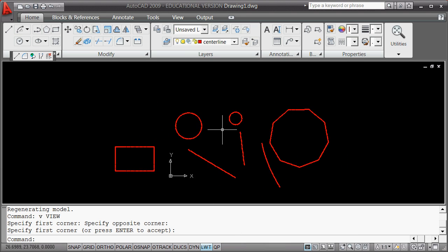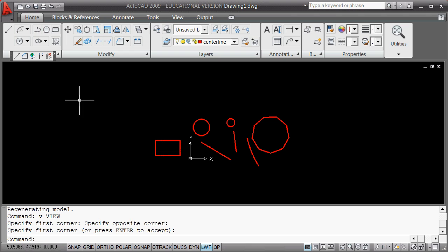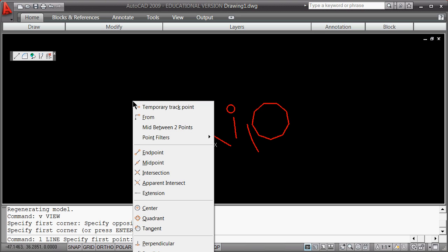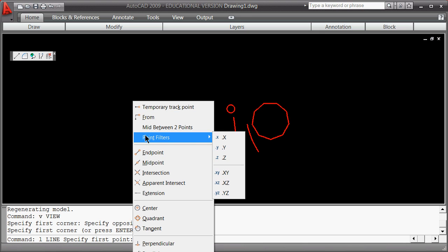Now I'm going to start drawing some lines using snaps. We do that, of course, by typing L. So I'm going to push this back out of the way, and I'm just going to tell you what I'm typing as I go through. L spacebar for line, shift right click. All right, so what are our choices? Well, let's skip these ones up here, which are kind of advanced-ish.